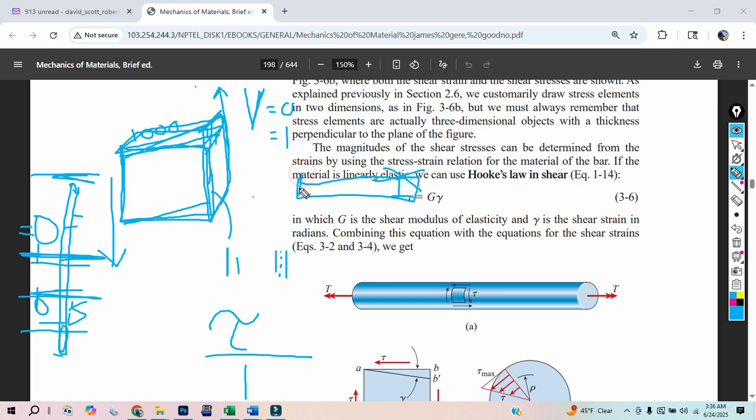That's why I hate engineering and physics. What I do in my head is, if I stretch a meter long steel bar 2 millimeters, in my mind it's broken, even though I know it's going to bend permanently. I can almost stretch it 5% of its length, which is 2 inches. That's crazy. It's going to be totally worthless after that. It's going to neck down, but it does pick up some extra strength.